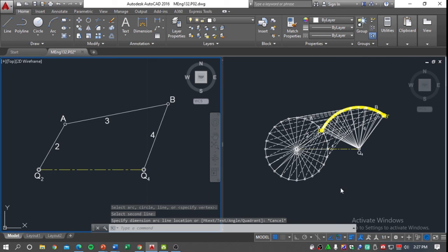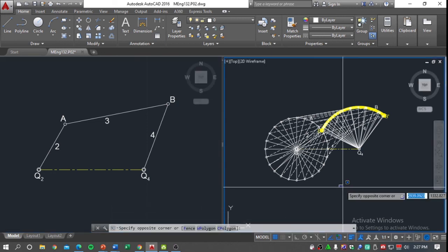So if we activate this four-bar linkage, for every complete revolution of crank 2, we can say that point B is oscillating with a maximum of 100 degrees, since we have just measured the angle between the extreme positions of point B.